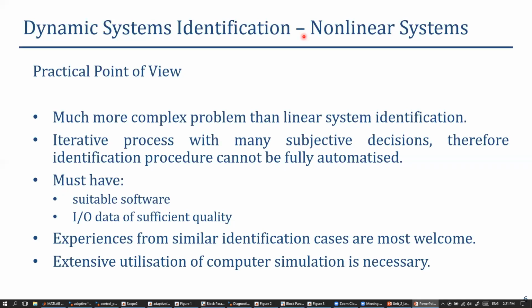It is important how to set up the experiments. Data is very important. Data is expensive. Remember that. High quality data. In our case, high quality data means data which represents the dynamics of the system in a wide frequency range. Experience helps a lot.